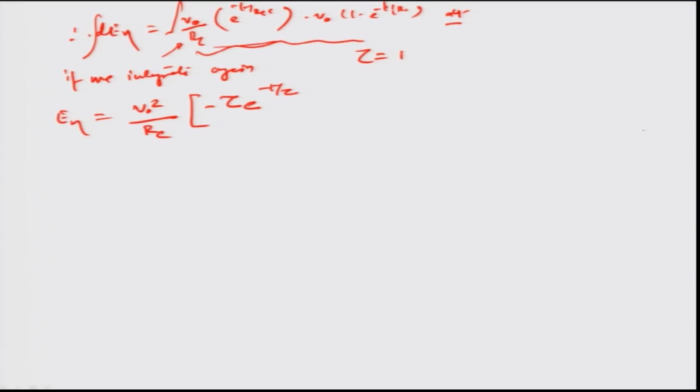We assume tau to be the time constant CRC, as just derived in the last step. So, I am just replacing this CRC everywhere with the value tau. So, minus tau e to the power of minus t by tau plus tau by 2 e to the power of minus twice t by tau plus the constant of the indefinite solution. Okay. So, constant of integration.